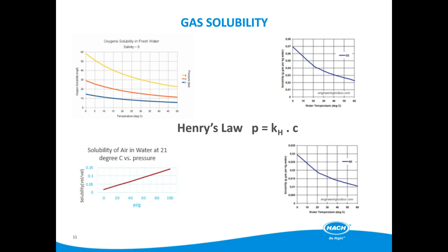the head space in the saturator soon becomes enriched with nitrogen, and eventually this will reduce the efficiency of gas transfer into the liquid phase by around 9%. This should be taken into account when calculating the energy efficiency of the DAF process.